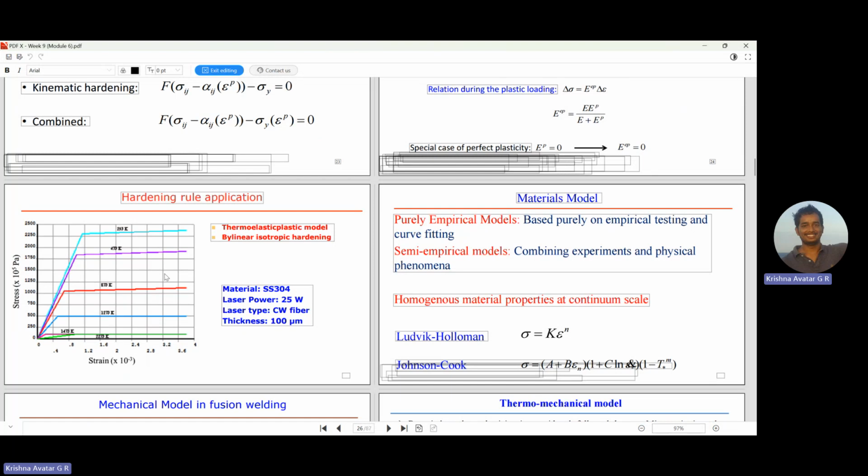Right now we see that even the thermoelastic behavior will also depend on temperature, where different temperatures will have different evolution of these materials. Intuitively, at higher temperatures, the material tends to become weaker. Of course, because if it's a metal, it starts moving towards melting, isn't it? That results in a reduction of yield stress, and you see in the graph that the yield stress is gradually decreasing